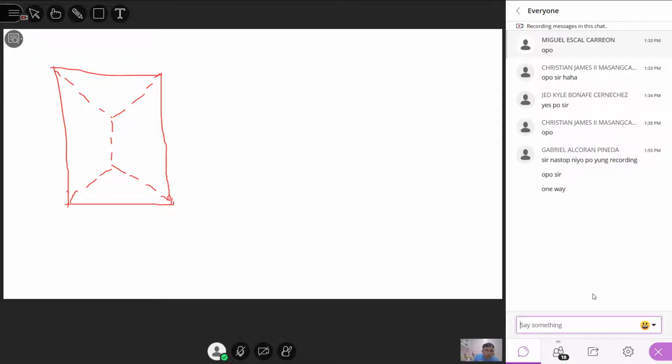So meaning, since it is a two-way reaction, there is load going in that direction, and you have another direction going there. So it becomes a two-way reaction. There are loads coming from the slab directed towards this beam, and other loads also going in this direction, and some going here. Again, this line of action is normally projected at 45 degrees.